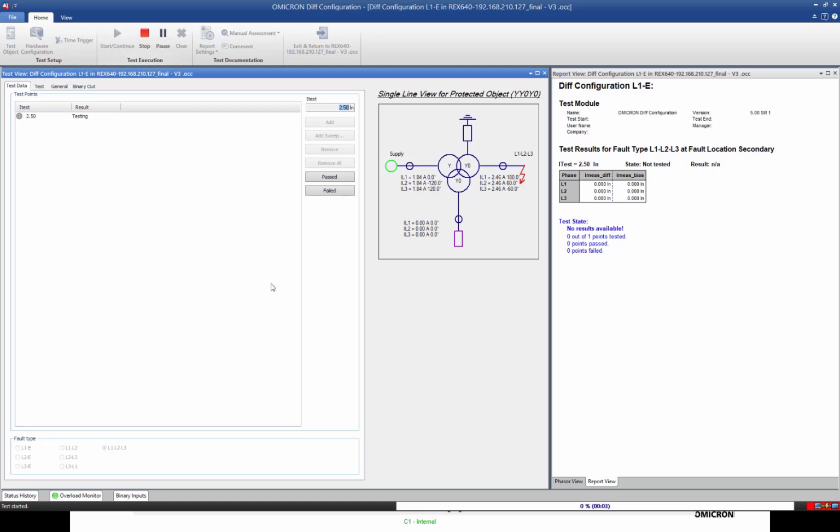As you can see, there is no differential happening. And how will the Test Universe know whether there is a differential or not? From the trip contact. Yeah, from the trigger condition. Also, you can see it visually from the relay if you need to make more sure.